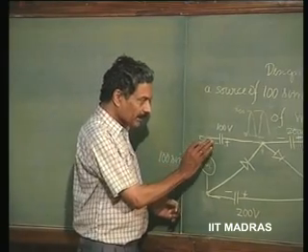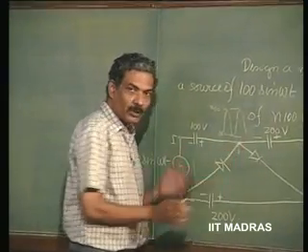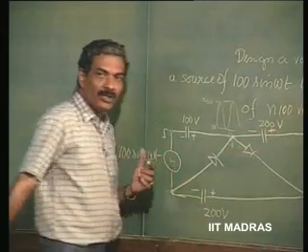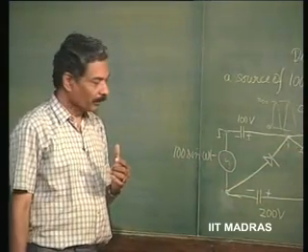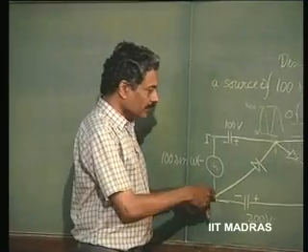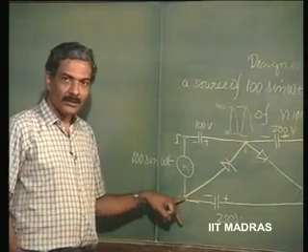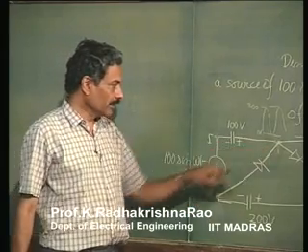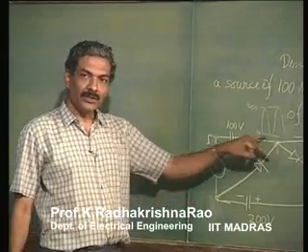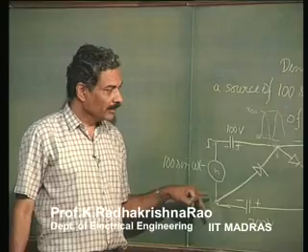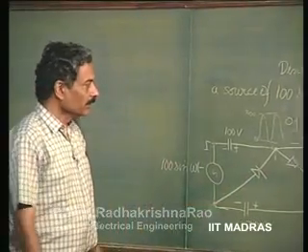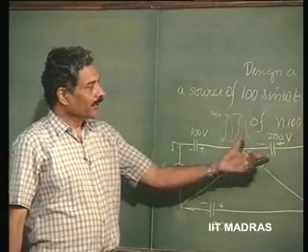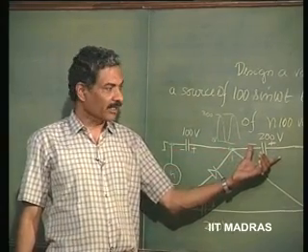The thing to remember here is that all these capacitors have to be good quality capacitors, so that they can sustain these 200 volts without any leakage whatsoever. And these diodes will also have to sustain the reverse bias voltage which is going to occur across them when they are not conducting, which is going to be about 200 volts again. So all these diodes should be capable of not breaking down at those voltages, and the leakage should be pretty small for these capacitors.